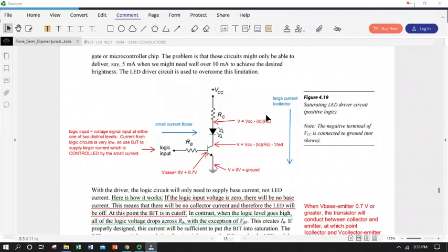There are several examples, and in fact the rest of this chapter, chapter 4, basically deals with different combinations and instances where we have beta control or we have external circuit control, and looking at what it takes to turn a transistor on or off based on our, pun intended, base current, and whether or not our base voltage is high enough to achieve that forward bias, usually 0.7 between the base and the emitter. So we'll see a lot of examples, and I'll go through some of these quickly. I'm not going to write them all out.